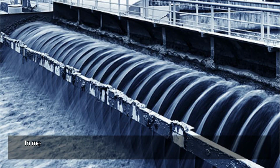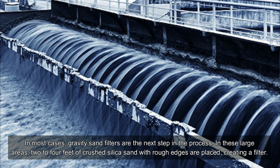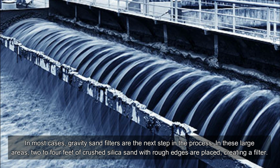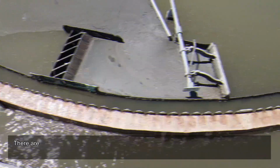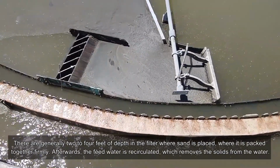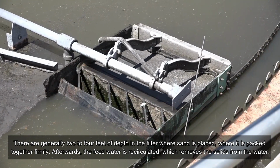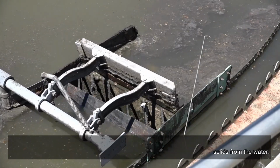Filtration. In most cases, gravity sand filters are the next step in the process. In these large areas, 2 to 4 feet of crushed silica sand with rough edges are placed, creating a filter. There are generally 2 to 4 feet of depth in the filter where sand is placed, where it is packed together firmly. Afterwards, the feed water is recirculated, which removes the solids from the water.